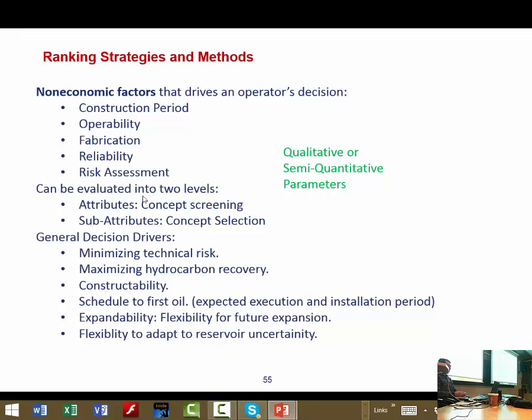As in our previous example, you don't know exactly how many risers you need. And if you want to increase the risers, for example, when you select an FPSO with a disconnectable turret, which is a very safe solution and one of the major requirements for the Gulf of Mexico. All the FPSOs should have a disconnectable turret.